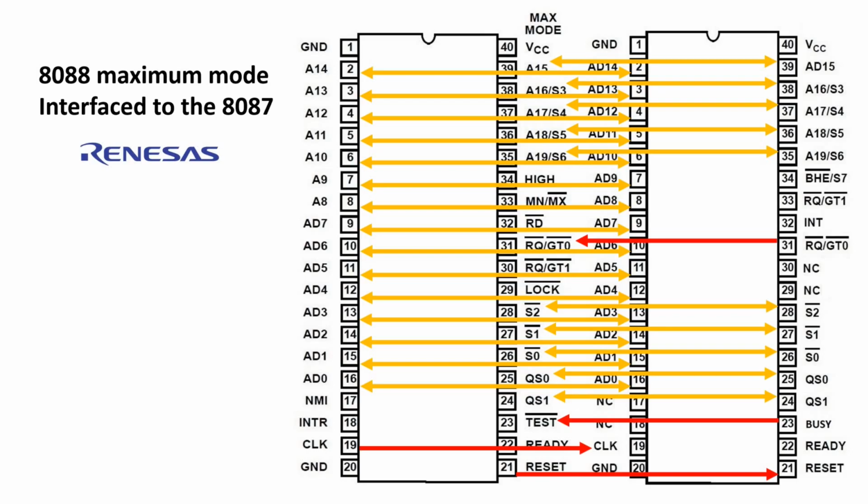It's clear that Intel designed the 8087 intimately with the 8088 and 8086 to be compatible in terms of how the bus worked, and also the pins are almost identically placed, which means that PCB layout is greatly simplified. And so you can see the yellow pins where there's a one-to-one mapping, and the red pins are ones where there is a little bit more significance. The pins are still shared.